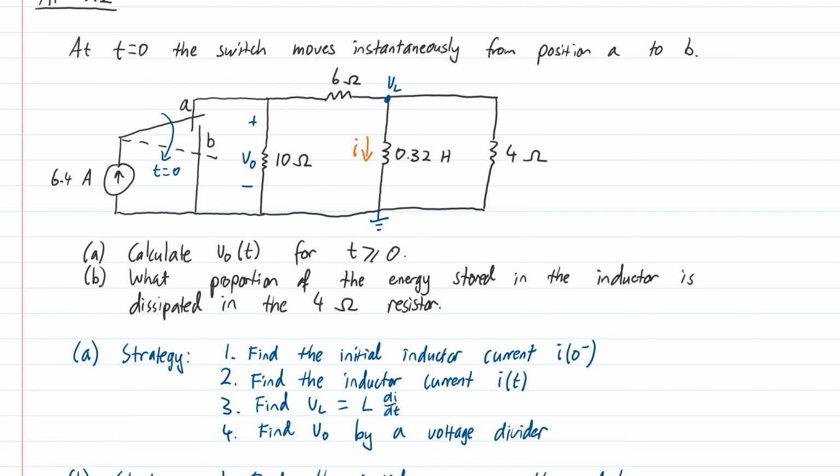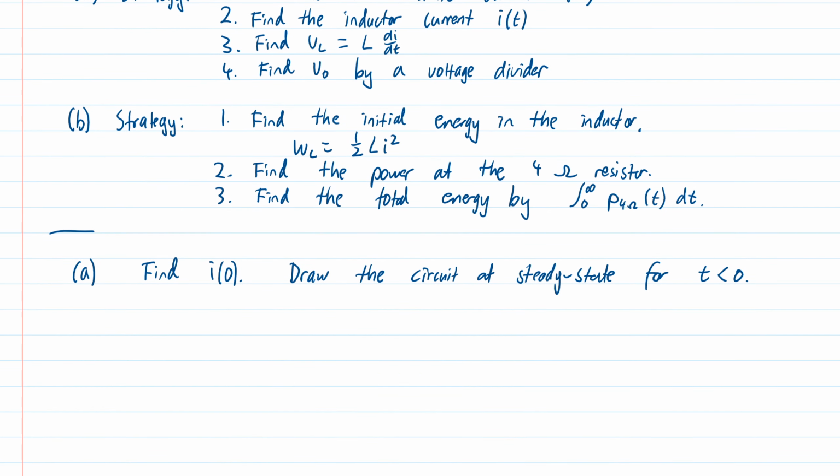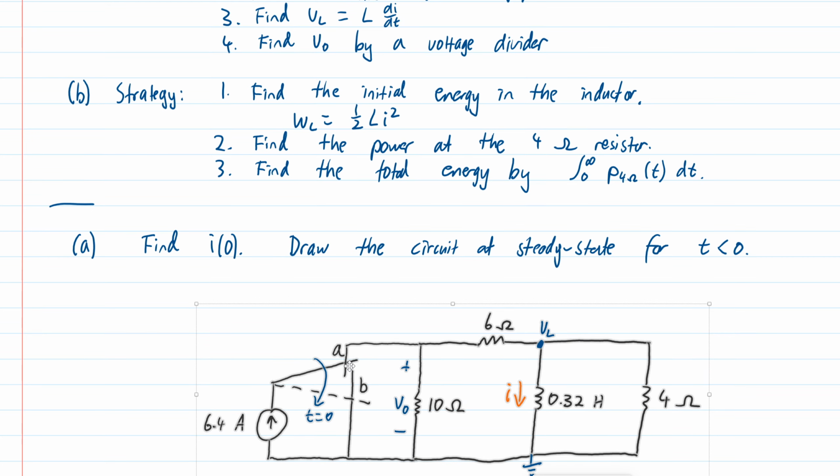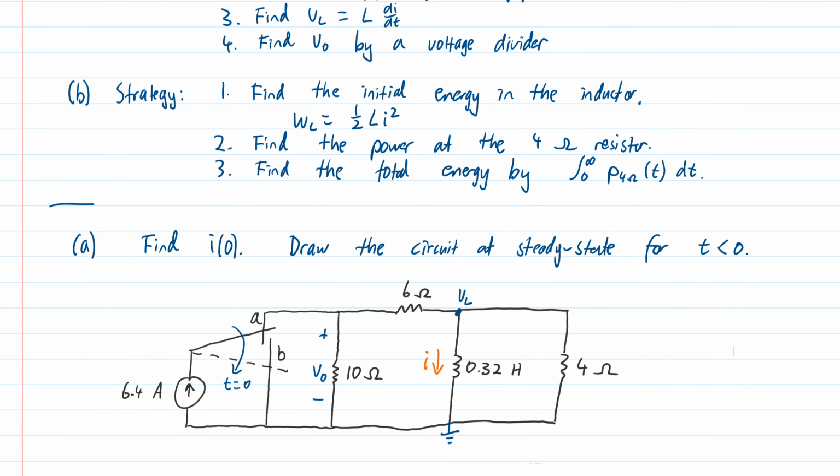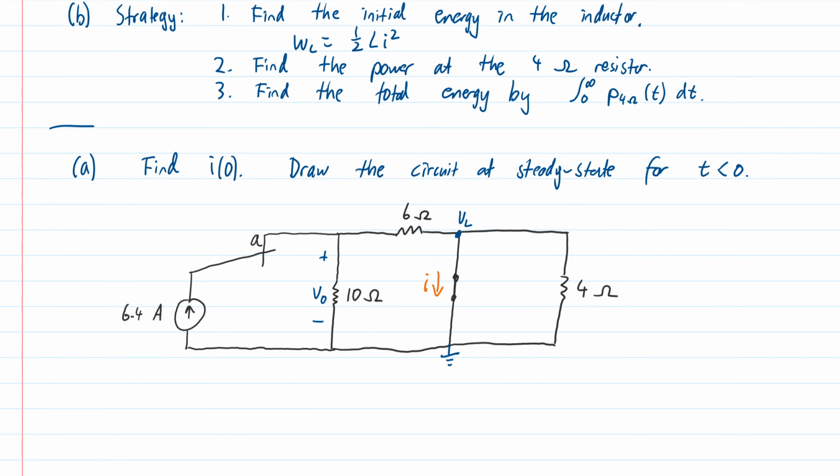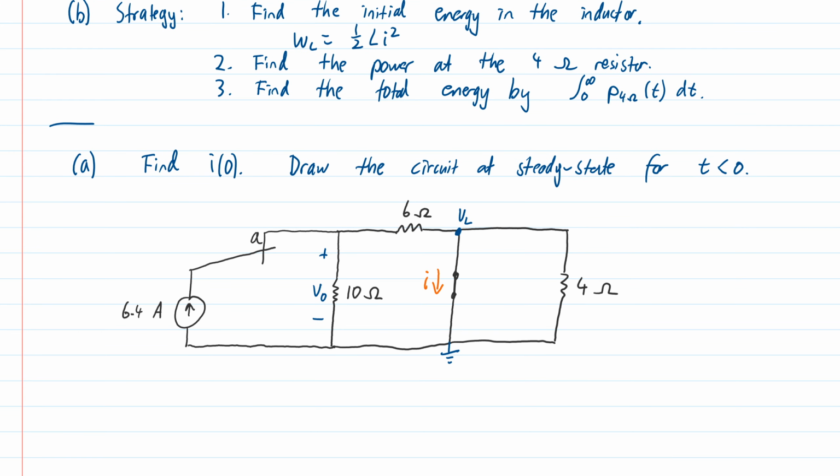So we have our current source flowing. What I might do is just take my diagram and redraw it down here, and we'll simplify the drawing a little bit. So we don't have this switch part, we just have the current source flowing directly in. And we replace our inductor with a short. So we have just this shorted through here. That's simplified things quite a bit.